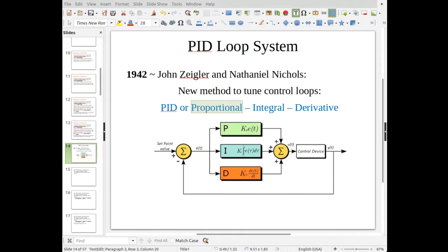When I say slow, the normal scan time of modern PLCs is maybe a millisecond, so that's not too bad. But when you try to calculate integration or derivative, now you've got to build in some extra time for this delta t piece.